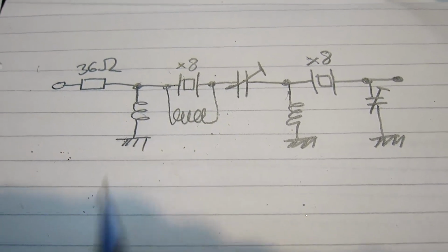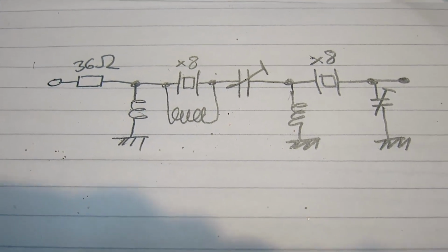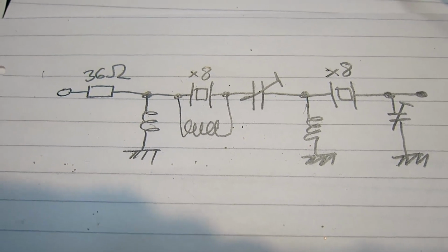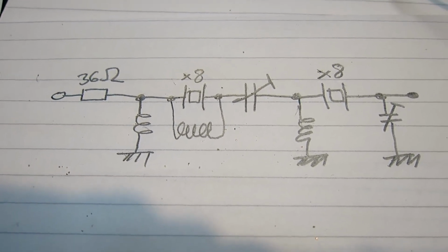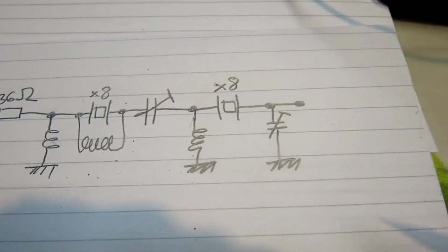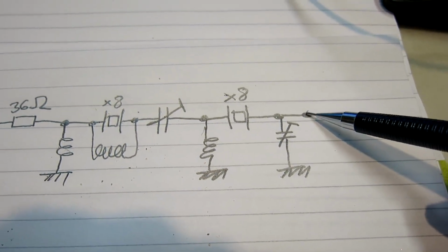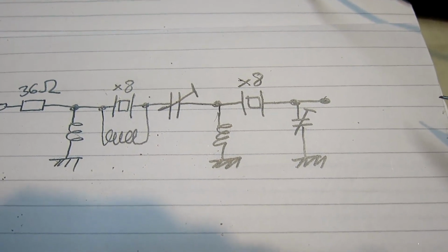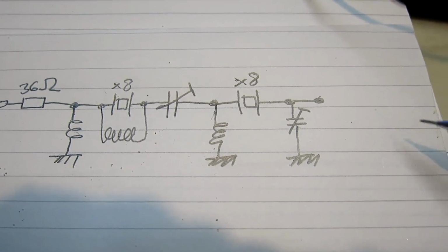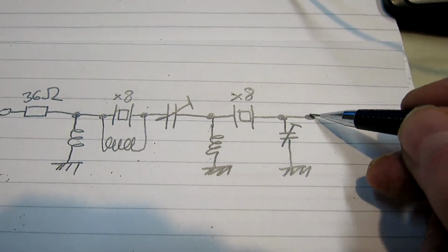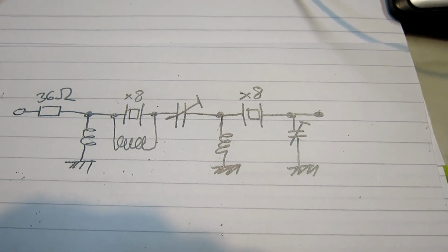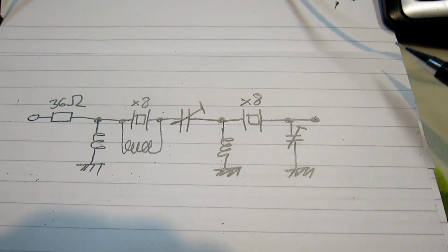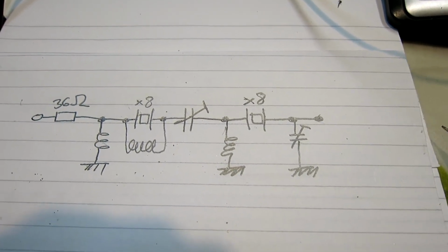I prefer inductors over capacitors because I'm unsure about the losses of such big capacitors at 10 megahertz. And then the output here is the high impedance point where I will put the junction FET transistors. I am monitoring this point now through a 2 pF capacitor, which is not loading this output significantly.